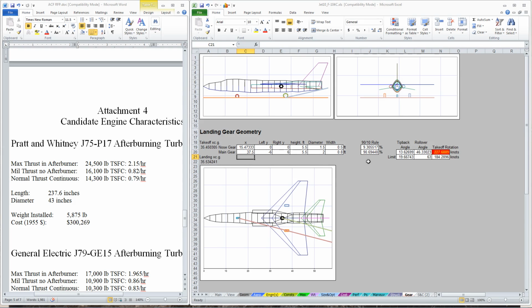And we've got a good, we can go, yeah, that's too far. That's 19 degrees. Let's go 37.2. 16, 17 degrees. Yeah, let's stick to 37. That's right at 15 degrees. We'll just make the gear a little bit taller, 5, or let's make it 6. And now we do have to go back again here, 37.3 or something. Alright, that's good.